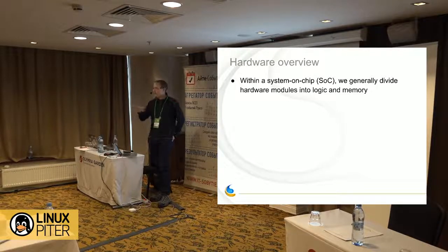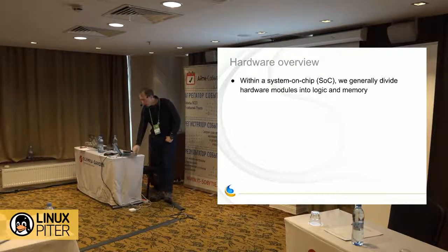Now let's move on to the electronics aspect, an overview of how the hardware works and how it's made. So let's start with the modules that are within hardware. Modules are the IP blocks or the functional blocks inside of a chip or a system on chip. They can be a CPU or a DSP, a GPU, I/O controllers, serial I/O, storage controllers, network devices, et cetera. A module is just an IP block. It does something functional, and it's typically composed of logic and memory inside, and we manage those a little bit distinctly when it comes to power.